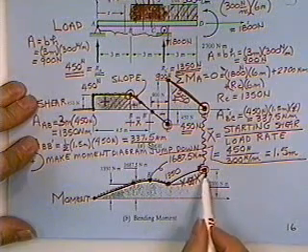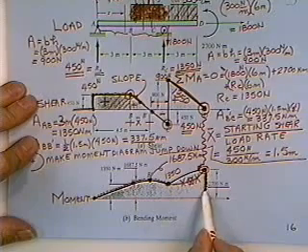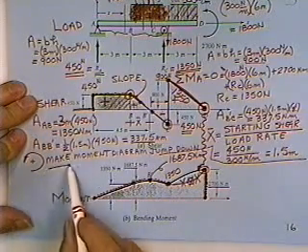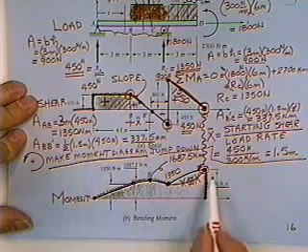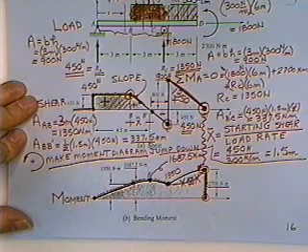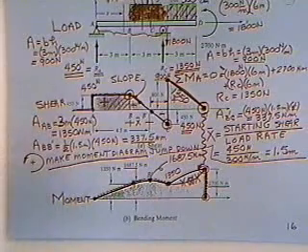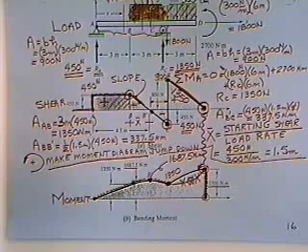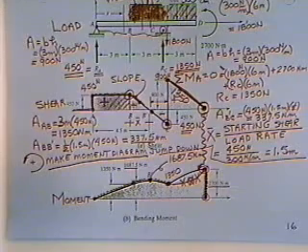Then the final thing is as you cross the concentrated moment, it makes the moment diagram jump down, and therefore the diagram closes on 0. Now, that's a lot of work, no two ways about it, and a lot of places you can make errors, but the number of problems that depend on shear moment diagrams was massive.